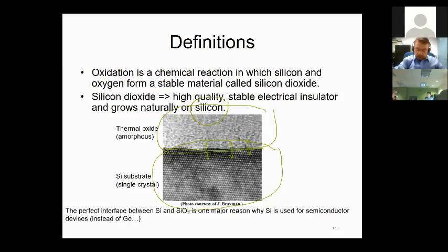And I can see one more drastic thing. I can count the atoms here on the silicon side. As you can see, they are the single crystalline structure, whereas at the top, for the amorphous, I don't see that kind of a nice continuation of a network. So that crystallinity has been lost there, as you can observe. And that's going back to our first lecture, the difference between the amorphous and crystal structures.